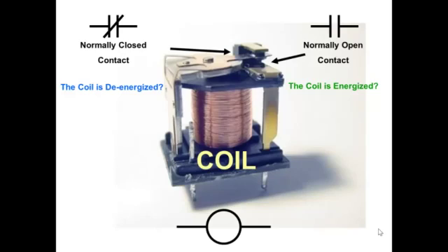In other words, you have a circuit that when the circuit completes, it energizes this coil. That circuit could be made up of many individual devices wired in series, meaning it could be 3 switches from 3 completely different locations in the process. They're wired in series, so all 3 of them have to be closed before the circuit is complete and energizes the coil.